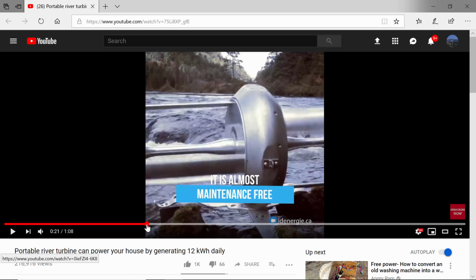And so when you've got some elevated water, that's potential energy. By the time the water gets into the pipe just upstream of the turbine, it's got a high pressure because the turbine's a lot lower than the water surface is, and so it's still potential energy. And then as the water flows through the turbine, what we have is an immediate drop in the amount of energy because there's a big reduction in pressure as the water goes through that turbine. The point is, the penstock, that pipe that connects the turbine and the reservoir, it's an enclosed channel.